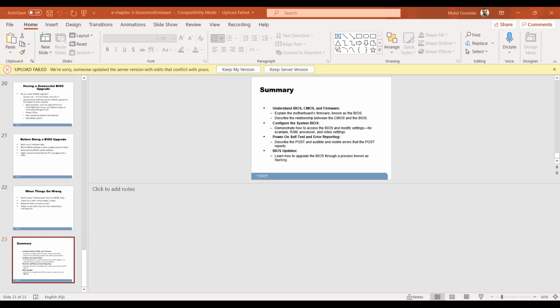If the problem persists after replacing the component containing cache RAM, return the original components to the system. The second option is to disable L1 cache. If the system runs normally, replace the CPU and retest. If the system runs normally after replacement, the L1 cache was faulty.